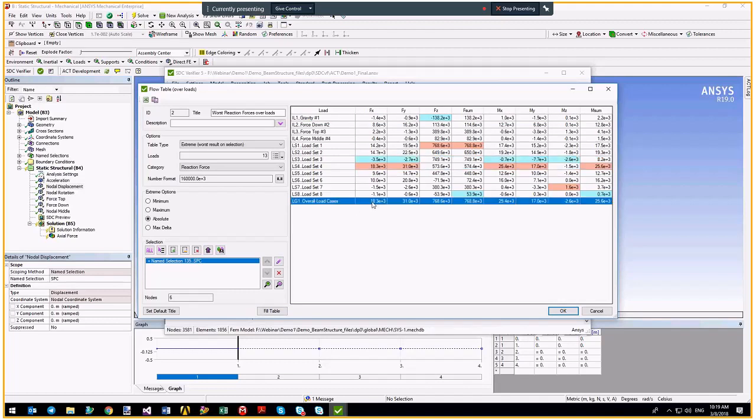As you can see, load groups show me the highest absolute results among all load sets included. So that's 18, and in this case that's 13. This from load case 4. And for example, in Z direction I have highest force from load case 1.